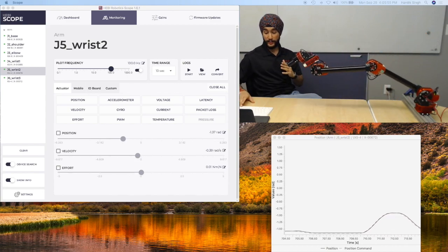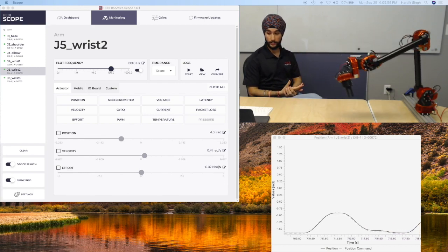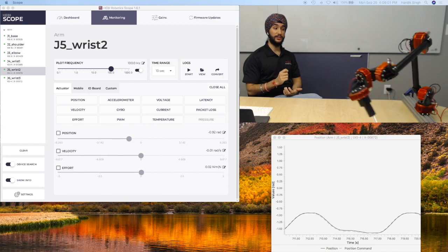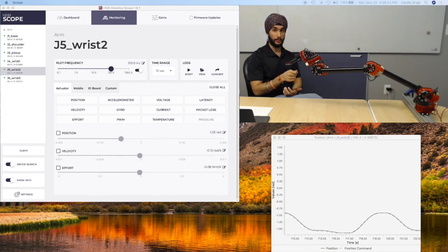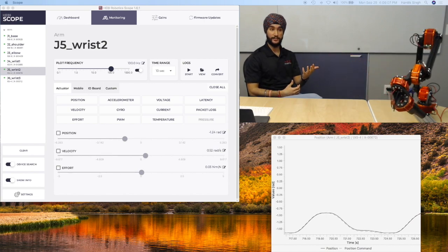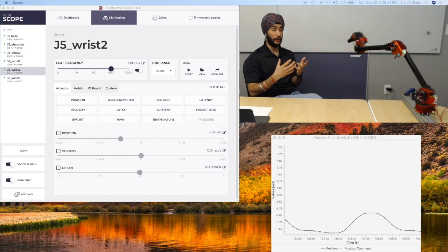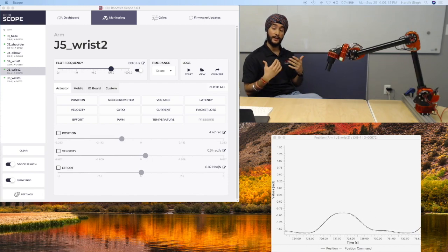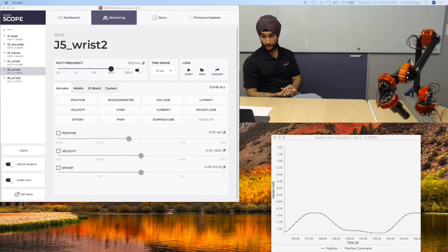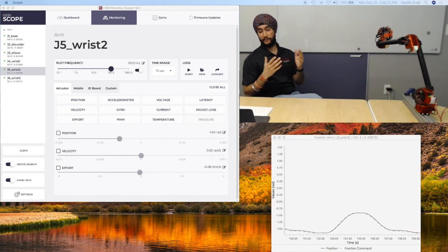Another thing I should note here is that you can really tune gains as much as you want, but you want to be tuning gains to your specific motion. I can't tune an arm beforehand and then suddenly feed it proper trajectories and expect it to be smooth behavior, because the control gains and the ability of the arm to follow a given trajectory comes after you've commanded that trajectory. Another thing is that tuning gains alone, as I mentioned earlier, is never enough.